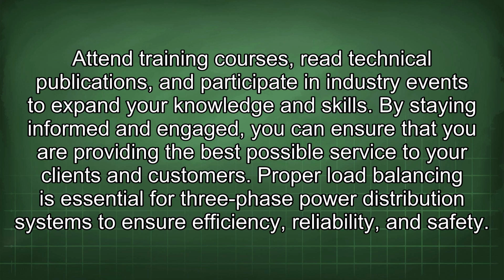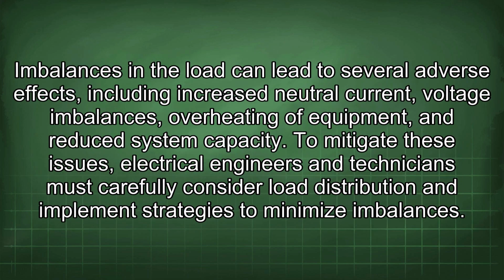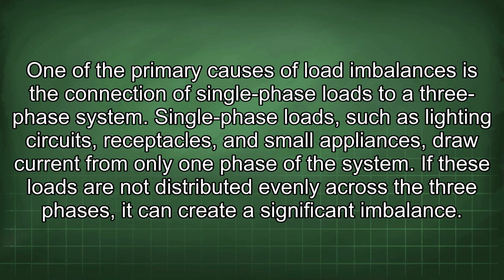Proper load balancing is essential for three-phase power distribution systems to ensure efficiency, reliability, and safety. Imbalances in the load can lead to several adverse effects, including increased neutral current, voltage imbalances, overheating of equipment, and reduced system capacity. To mitigate these issues, electrical engineers and technicians must carefully consider load distribution and implement strategies to minimize imbalances. One of the primary causes of load imbalances is the connection of single-phase loads to a three-phase system.